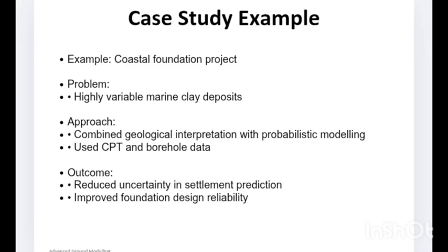You have to always keep in the back of your mind when you're handling a project that you need to understand the variability, the heterogeneity, the inconsistencies, the uncertainties that can pop up, and then integrate geological and geotechnical data. Those are lessons you need to learn, that we need to do a combined approach, and then manage uncertainty scientifically.